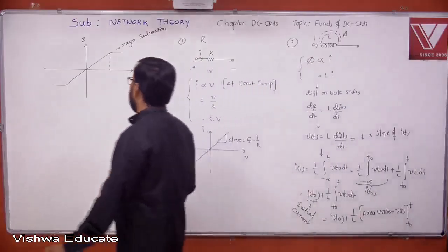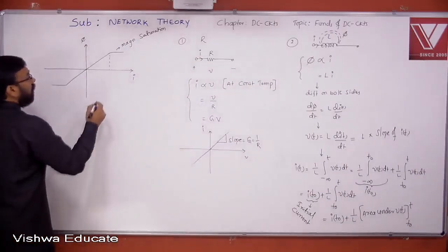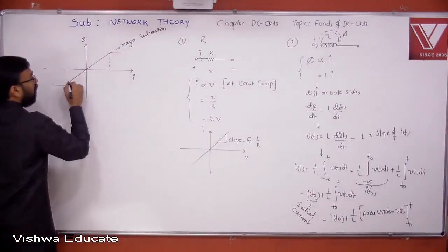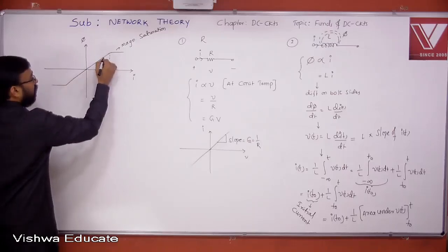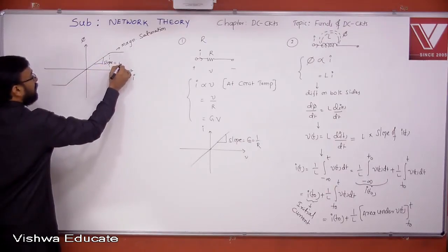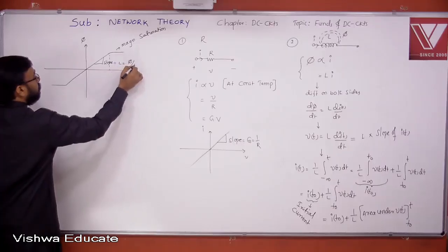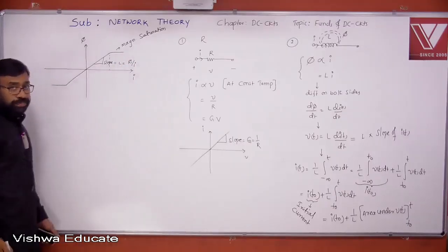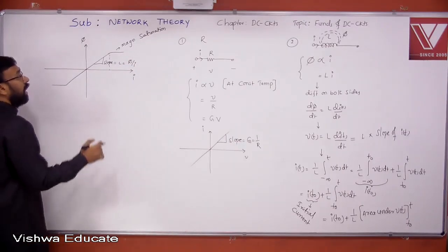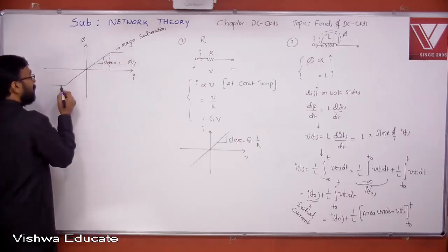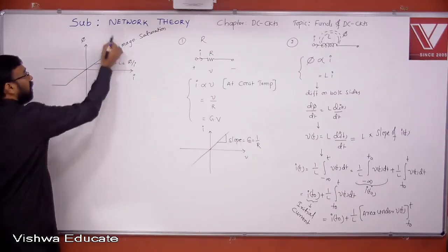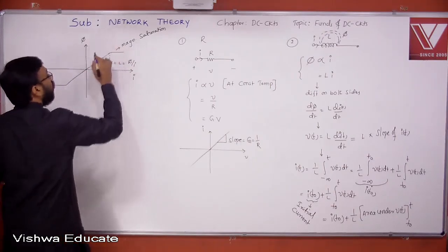Look at this, all of you. One important observation: if you neglect the saturation, you see all linear characteristics, and the slope can be calculated as L, nothing but phi by I. But if you include magnetic saturation in the characteristics, the whole characteristic looks nonlinear.